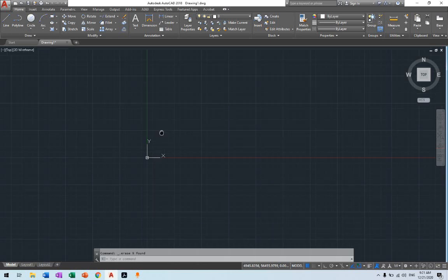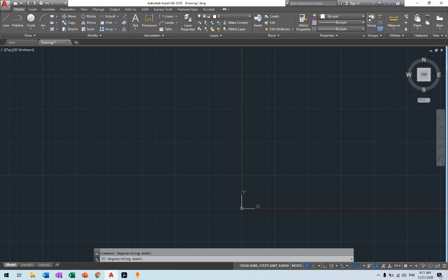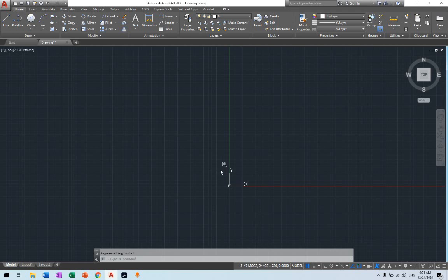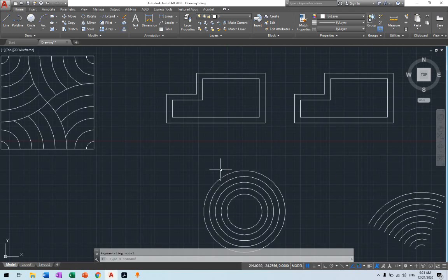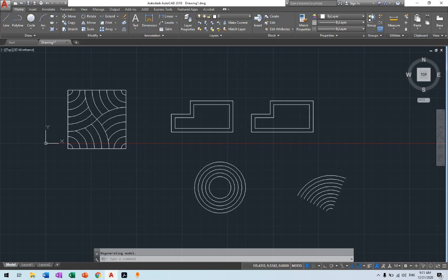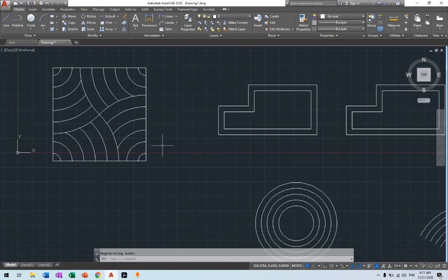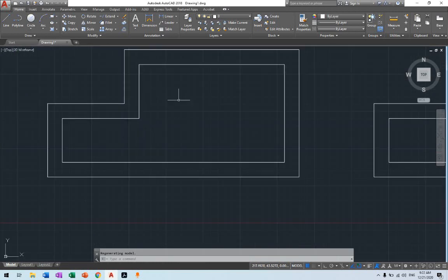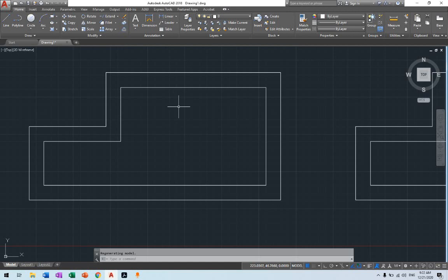How is offset going to help you? When you're trying offset, make sure that you see the pattern, that there are things repeating and the distance between them, you have it, then you can use offset for those purposes. Or when you see things doubling, especially the thickness of the object that we're drawing, or the wall, you can use offset for those purposes.